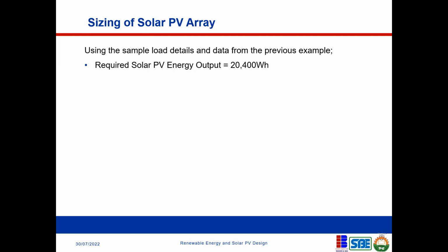So now we have sized the inverter, we have sized the battery. Let us size the PV system. Now remember, we started from the energy, then went to the inverter and the battery. We are now coming to the PV system, because you cannot start with the PV system and then go downward. It's the other way around: from the load to the energy, to the inverter, to the battery, and you now come back to size the PV system so that it can provide such amount of energy and power for those systems.